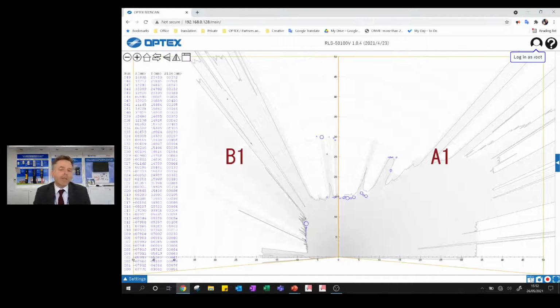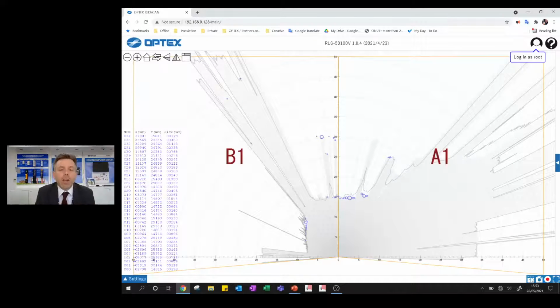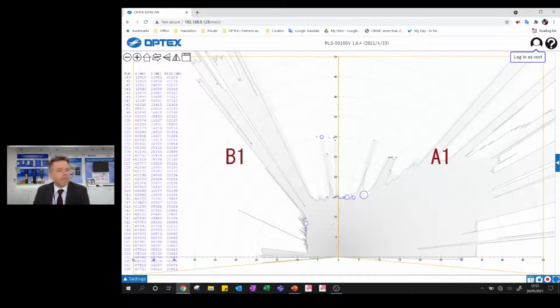That's really helpful, say during the day you have a large area that needs to be maintained, but you don't need to go into full alarm should there be an activation, but during the night you need it to go into full alarm. You're able to switch it by using a timer or a security system to give it an input, or access control system. You can switch the detection areas depending on your requirements. So that's a really helpful setting that we have there.